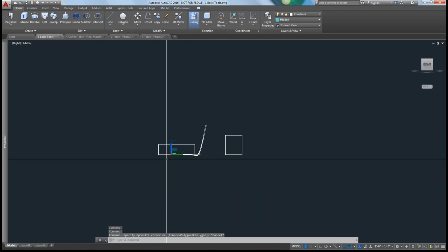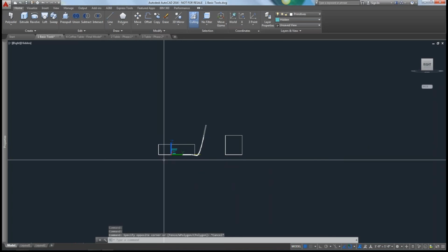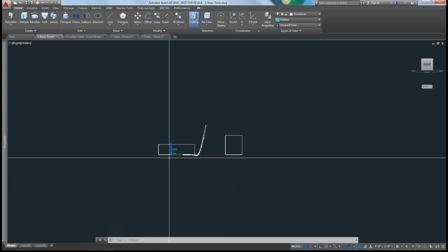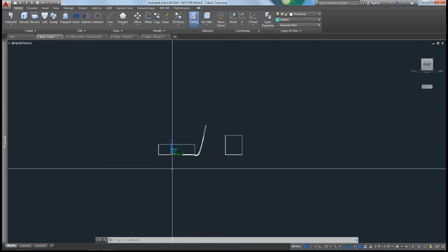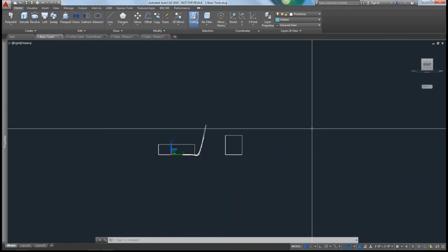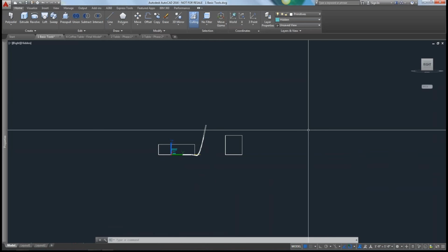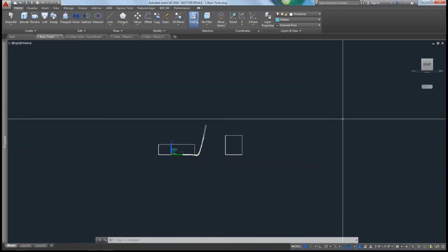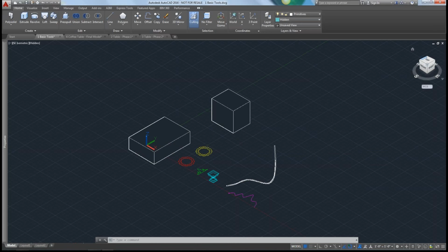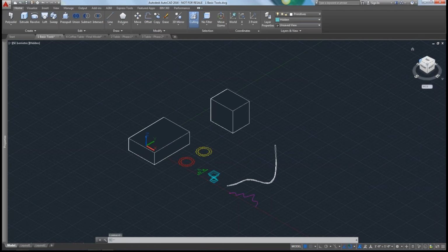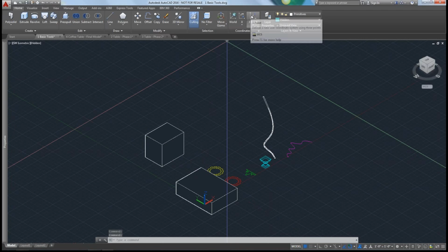Another thing you want to look at as well is whenever you move, your UCS will show accordingly. So right now I'm in the right side view, but my XY plane is still in the top view. So if you wanted to draw something on that side, you'd have to change your UCS, which you can do here. I'll just show real quick using a 3-point. Click on 3-point.